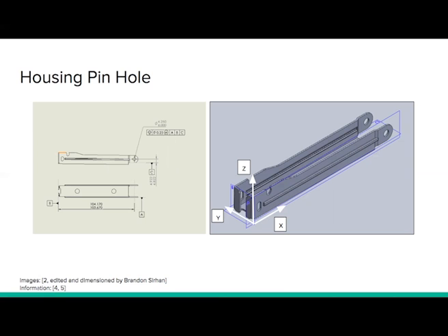For the size of the pinhole, the tolerance value must take compression between the axle pin and the pinhole into consideration. As the stapler needs to be opened in order to load staples, the axle pin needs to act as the pivot point for this motion to be allowed. It must be met with little to no resistance. Therefore, a lack of compression between these parts is ideal. This was also our main concern when choosing tolerances for the axle pin.